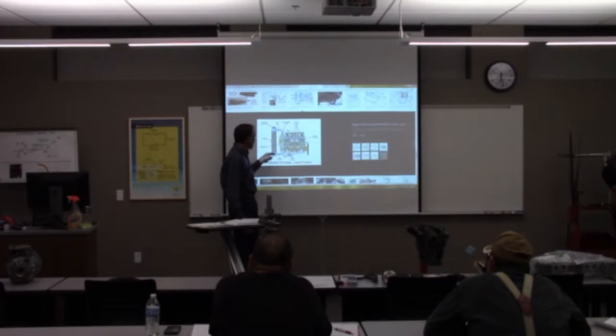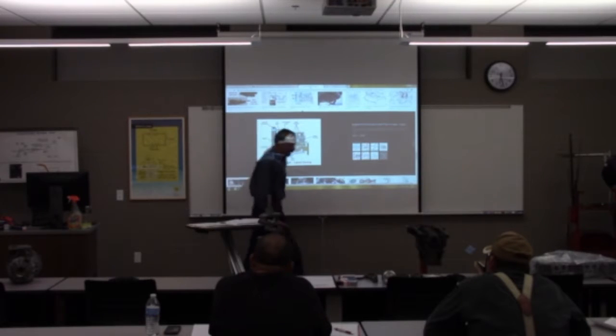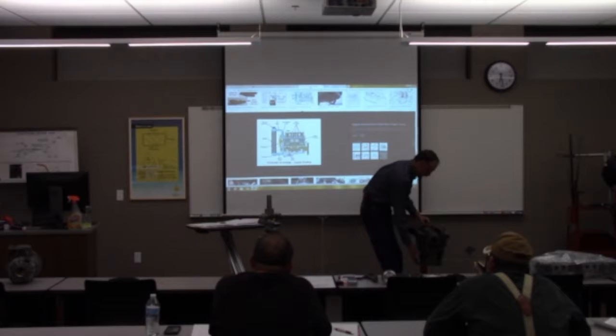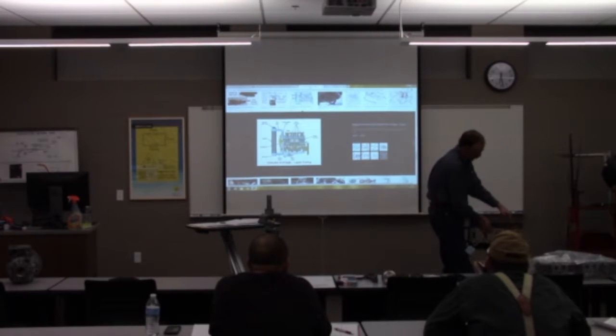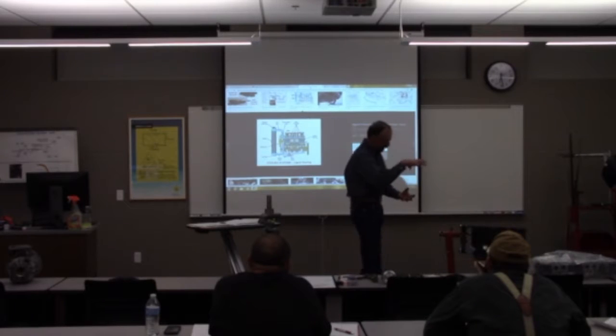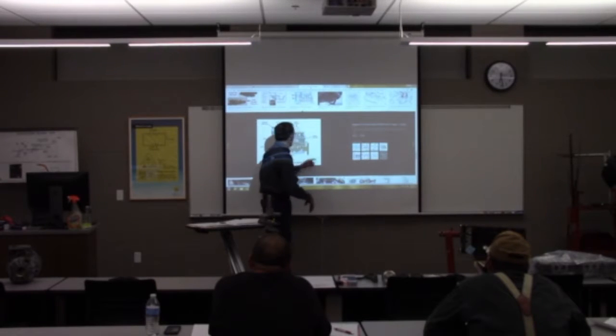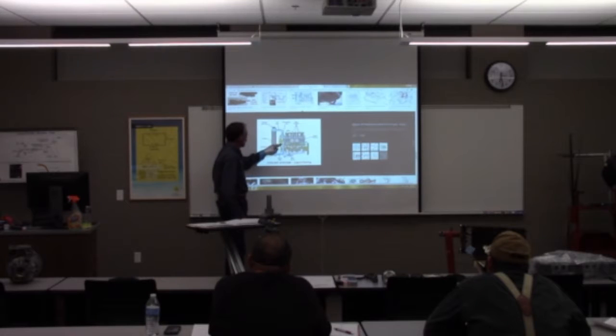So your bottom radiator hose will always be the water going into the engine. We're going to circulate it around all those cylinders. We're going to let it flow up, and as you can see in both of these blocks we have here, the water comes in the front, it circulates around all the cylinders, and then it comes up through these passages into the head, and it circulates over all the combustion chambers, and then we push it out the front.